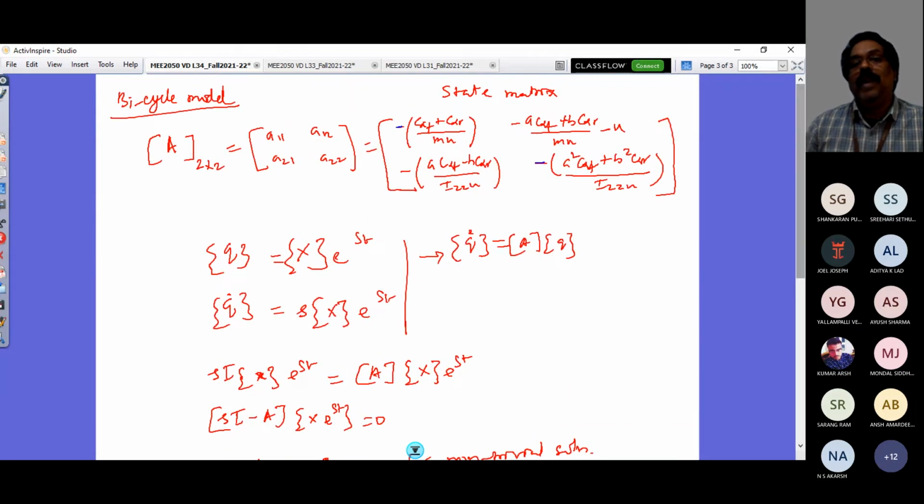So if you look at it now for my bicycle model, for yaw stability analysis, this is corresponding to this. So A naught is 1. If I carry out this, S minus this plus S minus of this, then A naught is 1 and A1 would be this minus of these two.